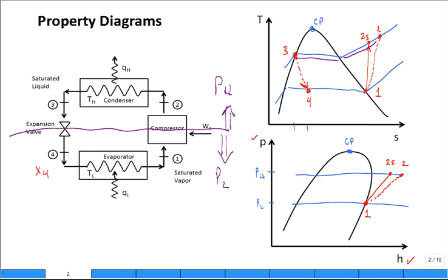That diagram line was a line of constant entropy, yes. Did I say enthalpy? No. It's a constant S, true? From 1 to 2S is constant S. And then you go ahead and cool it, so it's going from superheated vapor to saturated vapor, and then you continue to cool it until you get saturated liquid, and then at state 3, you're at saturated liquid, high pressure.